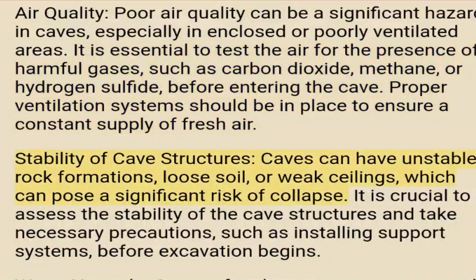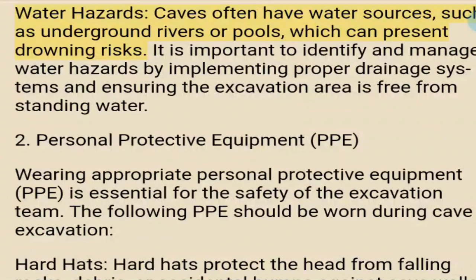Stability of cave structures. Caves can have unstable rock formations, loose soil, or weak ceilings, which can pose a significant risk of collapse. It is crucial to assess the stability of the cave structures and take necessary precautions, such as installing support systems, before excavation begins. Water hazards. Caves often have water sources, such as underground rivers or pools, which can present drowning risks. It is important to identify and manage water hazards by implementing proper drainage systems and ensuring the excavation area is free from standing water.